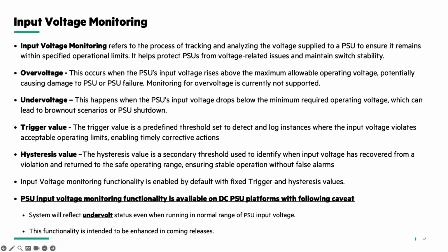Please note that input voltage monitoring functionality is enabled by default with fixed trigger and hysteresis values. I would also like to mention that PSU input voltage monitoring functionality is available on our DC PSU platforms with the following caveat: the system will reflect undervoltage status even when running in the normal range of PSU input voltage. This functionality is intended to be enhanced in a forthcoming release.